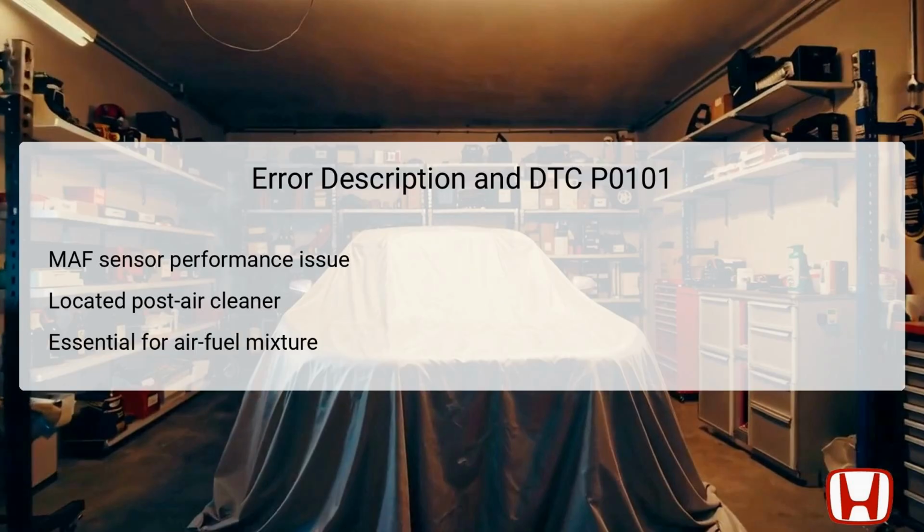The DTC P0101 pertains specifically to the MAF sensor's range and performance. This sensor directly measures the volume of air entering the engine, which is vital for the engine control module, ECM, to calculate the precise amount of fuel needed for combustion.